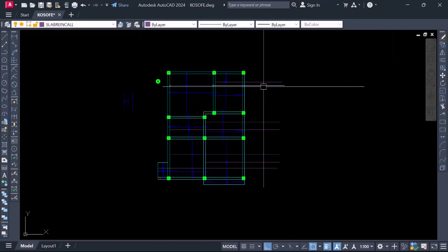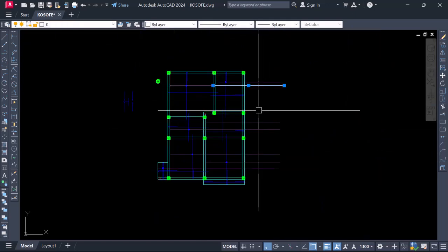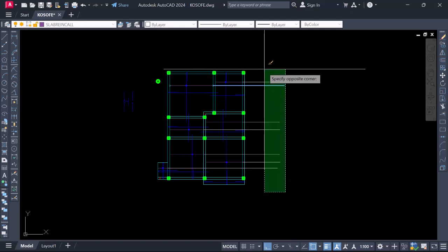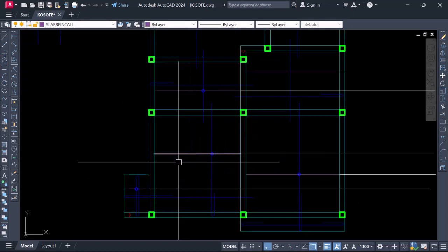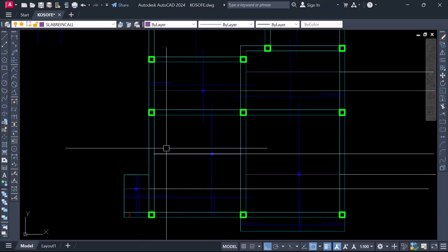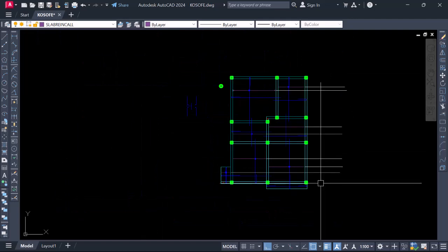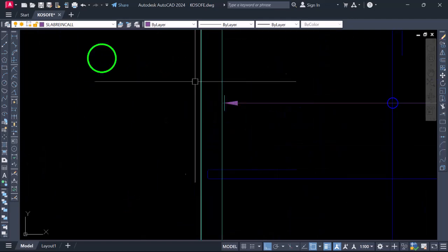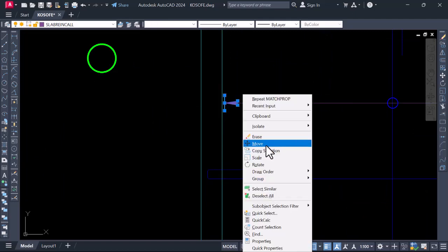Okay, let's match the similar properties so that we understand the ones that are actual, the span line and the label line. You can see the one in this color is actually the span line, telling us that each of the reinforcement is running from one direction to the other direction, and this is a call out label, right? This is a call out label to this. So we successfully did this. So let's copy the direction arrow.